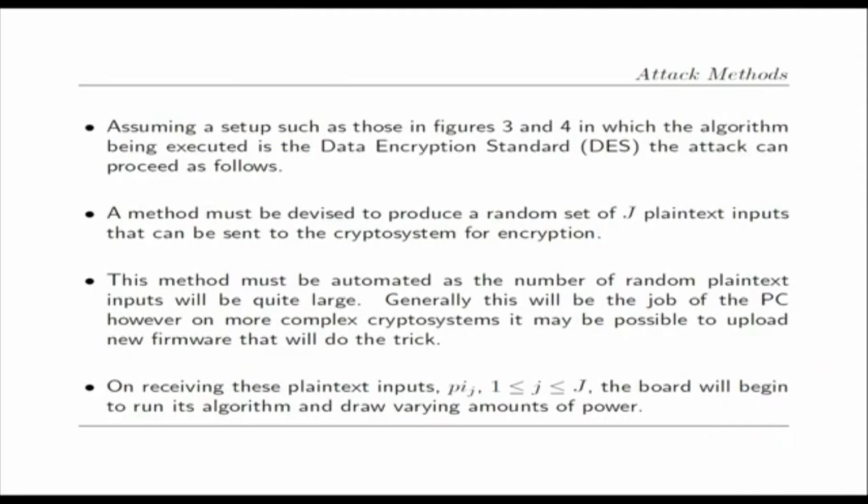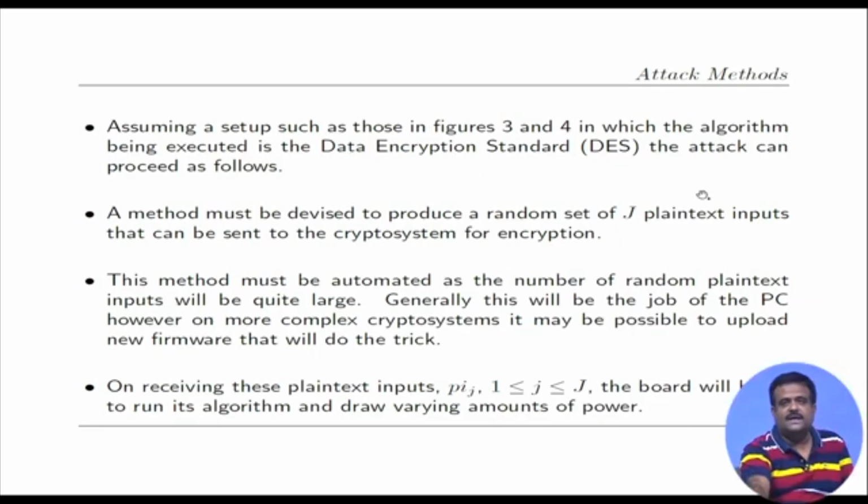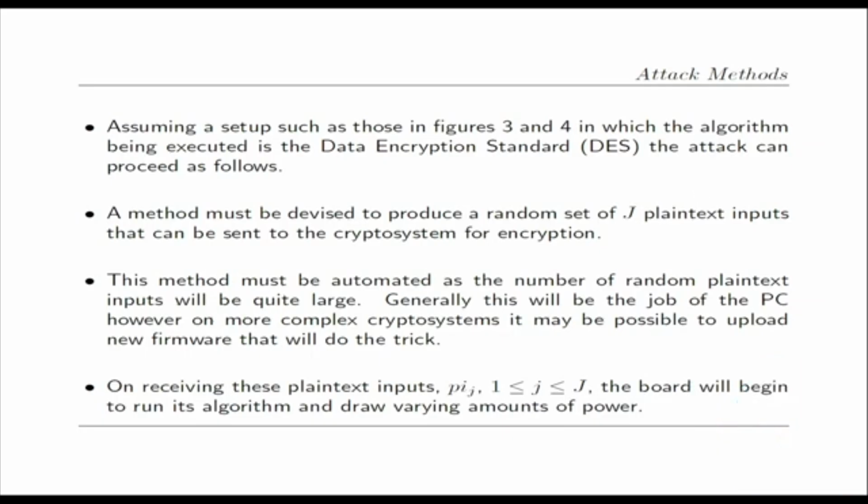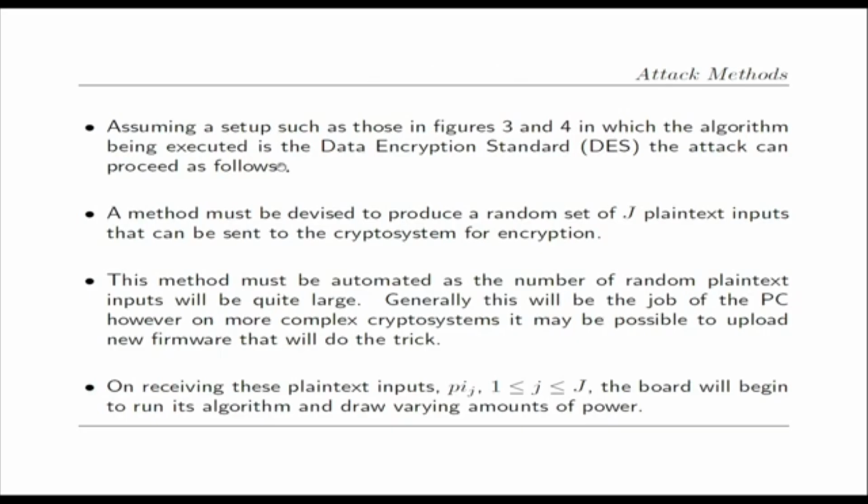Okay. So, assuming this setup, either 3 or 4, we want to apply this on the DES, the data encryption standard algorithm, for this differential power analysis. For that we have this setup, this differential power analysis model, we have the chip, and ultimately the power consumption or power fluctuation signals should go to the computer. Okay. To attack this DES, data encryption standard, this is the differential power analysis on DES.